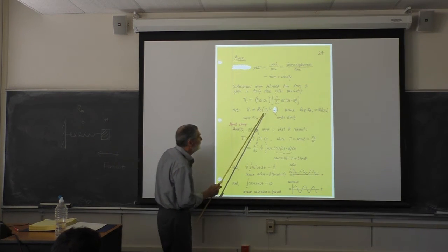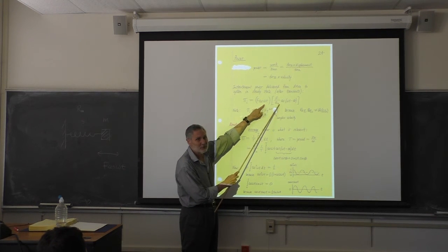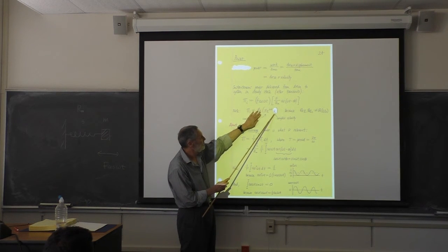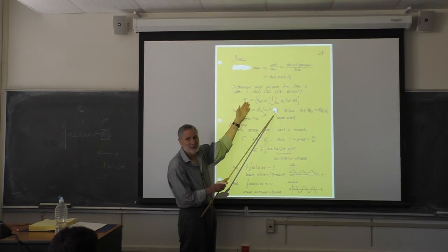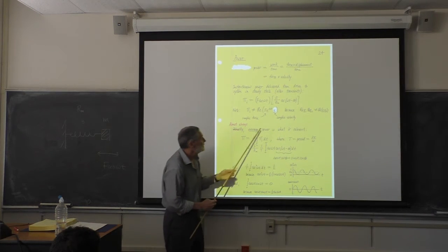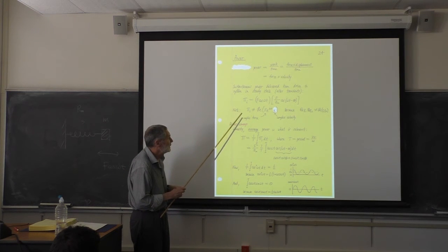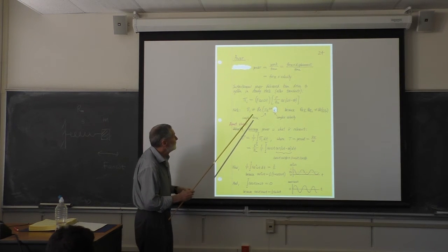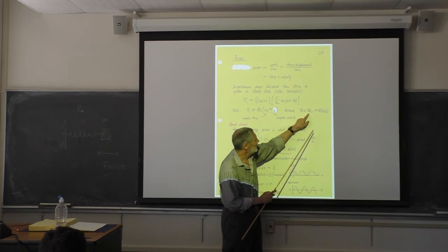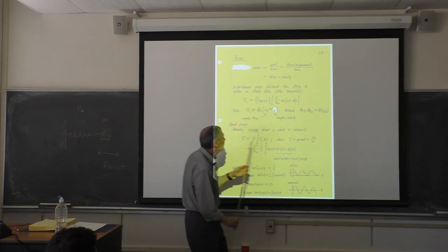And by the way, you need to take the real parts before you multiply them. If you just multiply the complex force times the complex velocity, you will have made a mistake. Because remember, we did a homework problem: you can't commute these operations. Taking the product and the real part, we have to do this, because this is the proper thing. It's not the same as the real part of the product of the complex numbers. So you've got to do it this way.